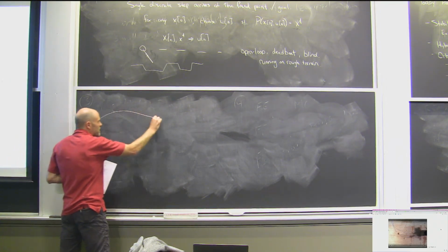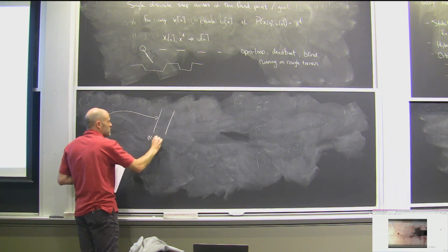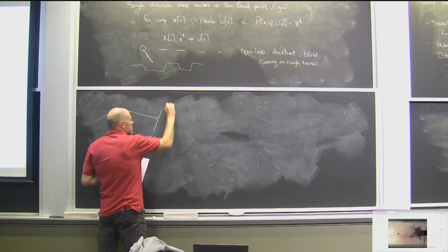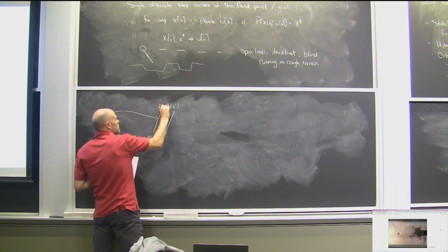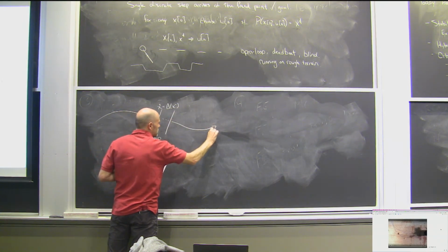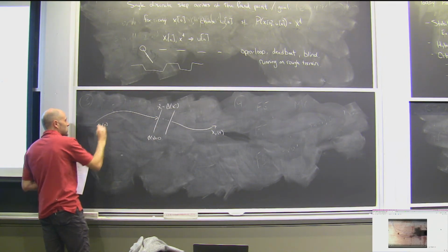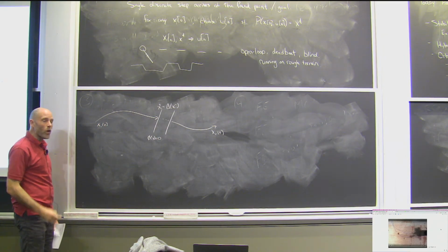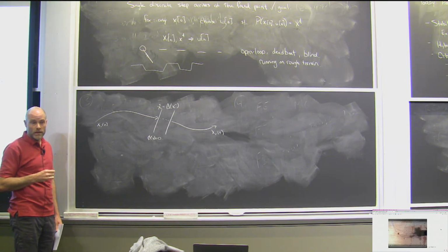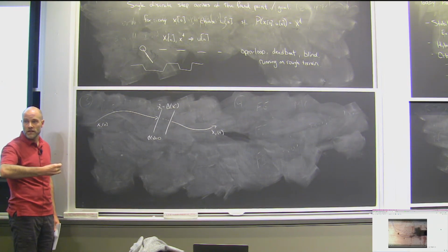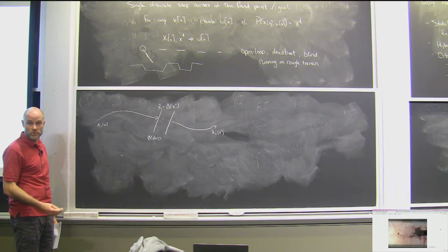All right, so in my picture here, we already know how to do time-varying linearizations and get a time-varying Riccati equation and then therefore a time-varying LQR solution, okay?